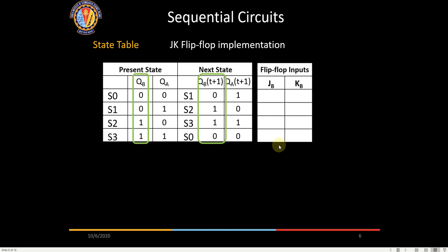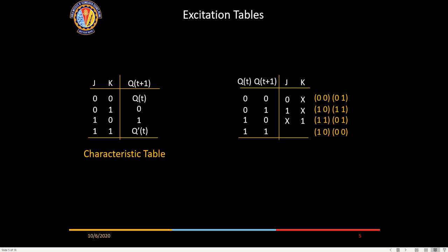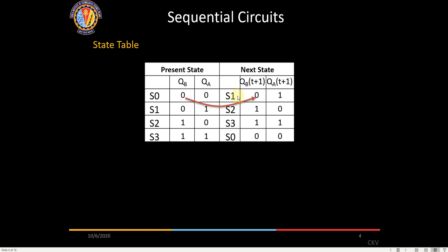So we are now taking one JK flip-flop. This is nothing to do with the circuit, we are speaking just about the JK module. The initial state is 0. When the clock comes, it has to change. Initially 0 here, only a single flip-flop. We require it to be 0 in the next clock. That means we have to make a transition from 0 to 0. So that means there is no transition required for this particular state, right?